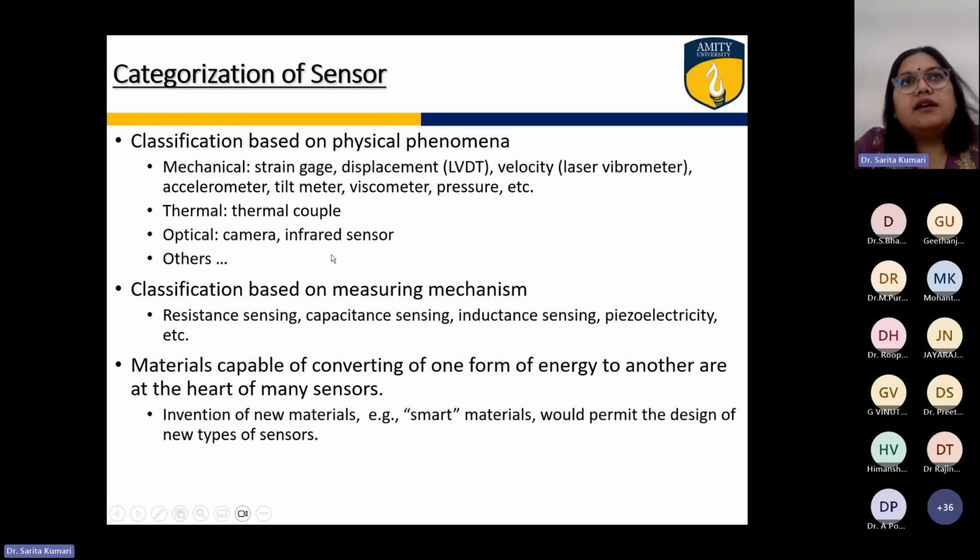As I said, when we are working at very high temperature, in a steel plant for example, where the molten steel has a very high temperature, it is not possible to measure the temperature with the help of a thermocouple. So in that case, we use infrared sensors or infrared pyrometers. That is the term used to measure temperatures above 2000 or 2100 degrees centigrade.